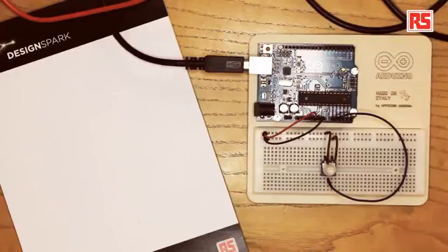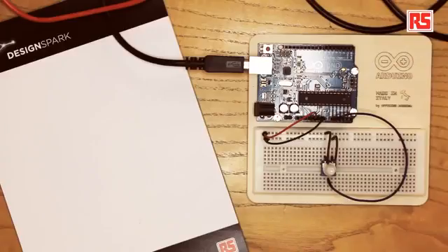There is a button on the Arduino IDE called Serial Monitor. If you press that, a small window opens up, and then you can see all the data that comes from the Arduino board scrolling down the small window. There is a little menu at the bottom that normally says 9600, and that's the speed of communication used by the Arduino to send the data. So the Arduino speed of sending and the Arduino IDE speed of receiving have to be the same in order to keep the data readable.